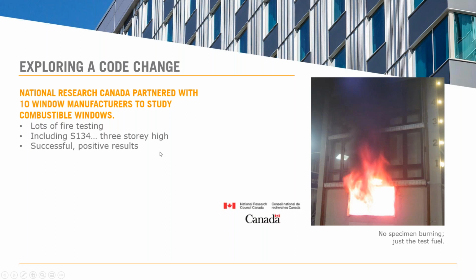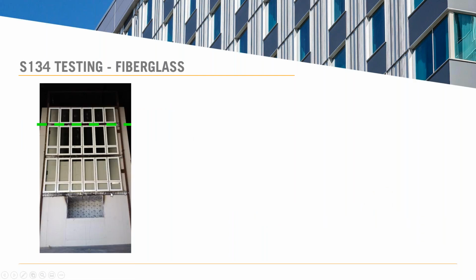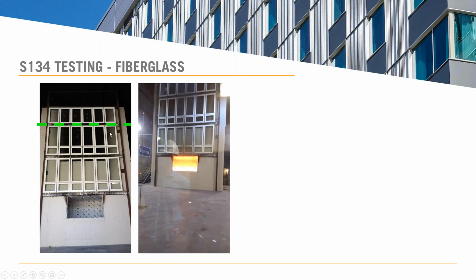So a lot of fire. And really the goal here was to prove equivalency to aluminum. And here's what the test entailed. You had a blowout fire in an apartment with a 3-story facade, and the fire couldn't reach past the 5-meter mark. There's other metrics as well, like temperatures and these kinds of things that were measured, but that was a real big pass-fail criteria there.